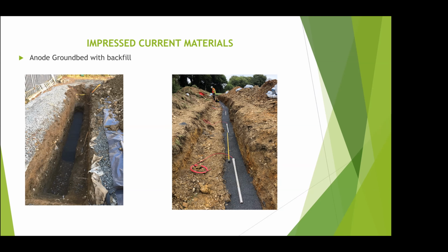And you can see there the guy's been measuring the distance between the anodes because we will have calculated how far apart they need to be to operate without interfering with each other. I should have mentioned there are two laws really, not just Ohm's law. Ohm's law is very important, but the one that trumps Ohm's law every time is Sod's law or Murphy's law. And that tells you that if you put these anodes too close together, they interfere with each other and reduce the total output. So we have to calculate how far apart we need them.